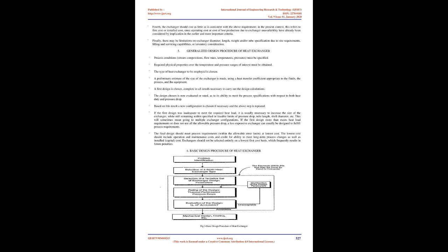Thermal conductivity of 0.5 Cr alloy tube equals 42.3 W/mK. Outlet city water temperature equals 25 degrees Celsius. The maximum flow velocity through the tube is also suggested to be 2 m/sec to prevent erosion. 3. Literature review. Wilfried Roetzel and Chakkrit N. A. Ranong calculated the axial temperature profiles in a shell and tube heat exchanger numerically for given maldistributions on the tube side.